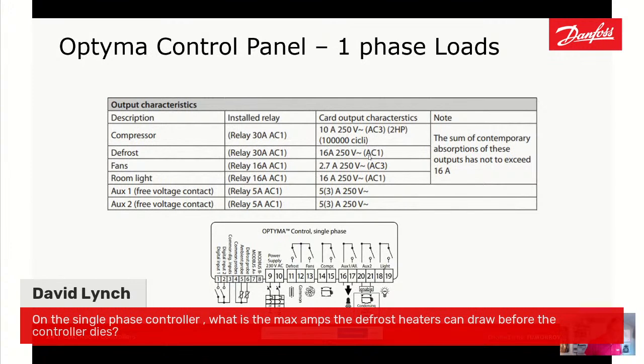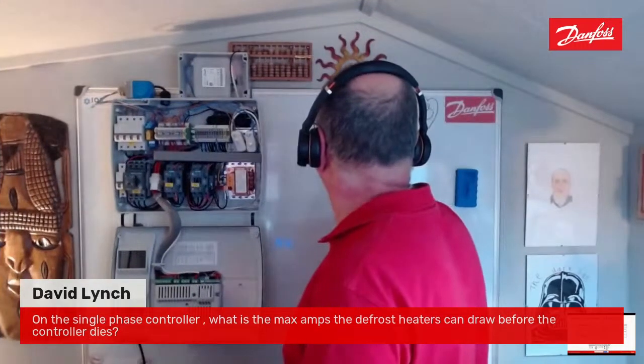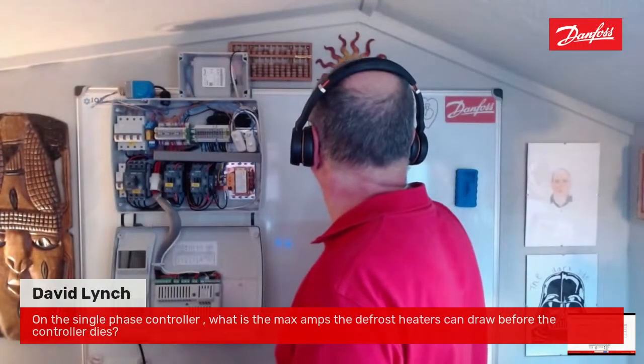So if we do a simple calculation, and my maths is not very good, 240 times 16 gives 3.8 kilowatts as our maximum load, David, that we can pull on that. So that should be enough for a decent size evaporator.